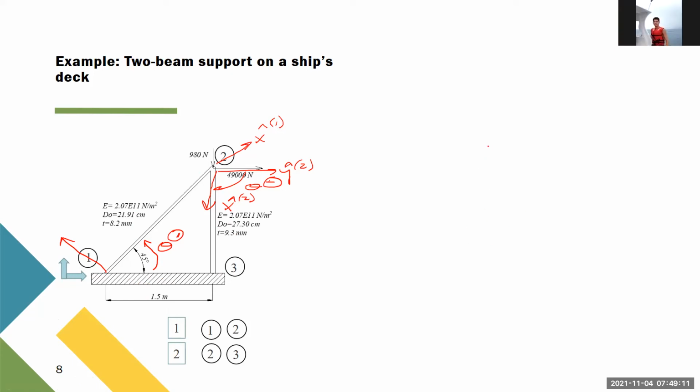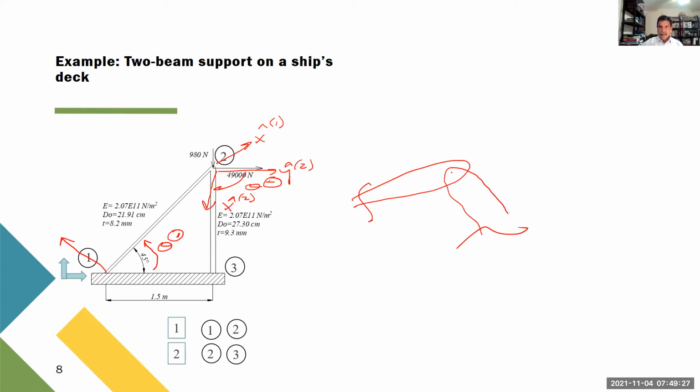Doctor, I have a similar question. In the joint 2, what are we considering? It is a clamped between the 2 elements. See, when I write something like this, and I put a dot here, that's a pin. This is a pin. And the pin, remember, this is something you have been working since solid mechanics, does not transmit what? Moment.